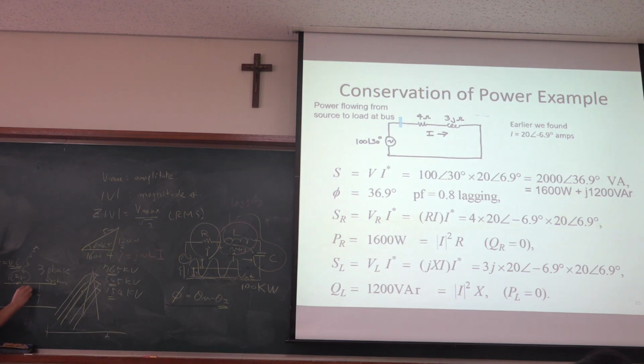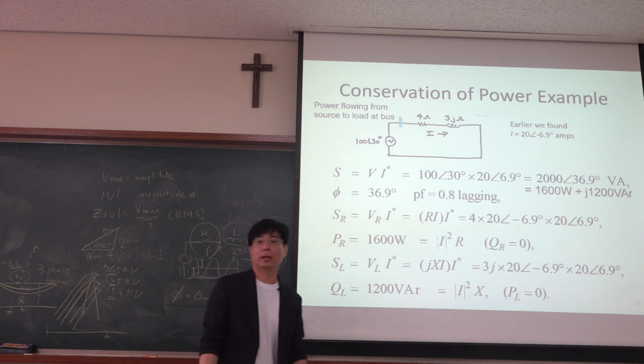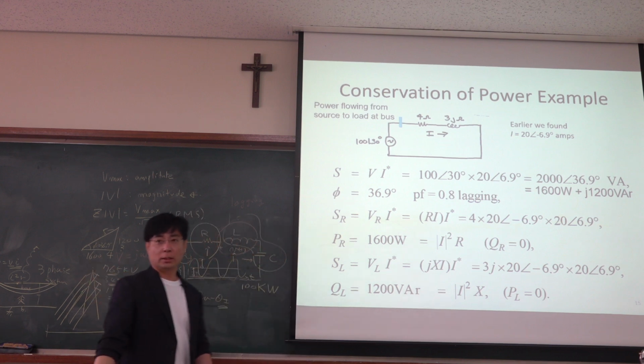Heat is generated here, right? And then the temperature of this line goes up, and then the line sags, okay, and then it can be further sagged, and then maybe there are trees here, and this sagged line can touch this tree. This is very high voltage, this is 0 voltage, and this wood is kind of insulated, but if the voltage difference is so high, then current can go through from here to there, right?